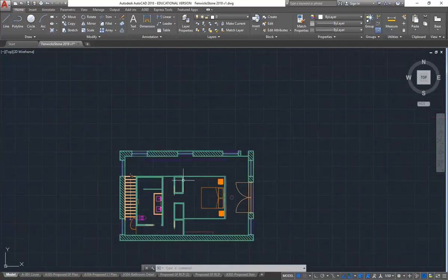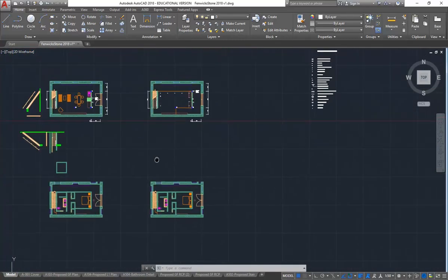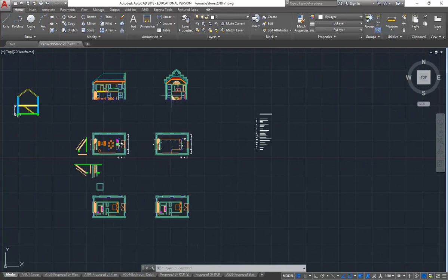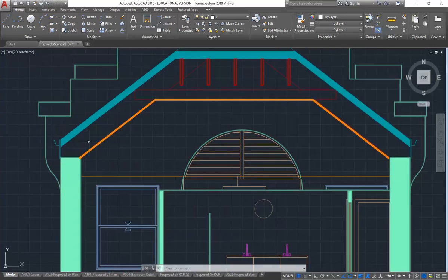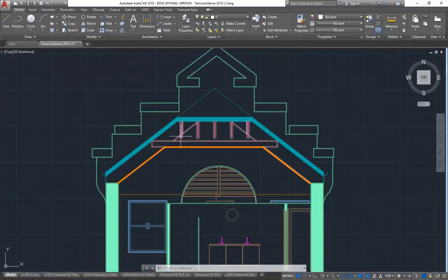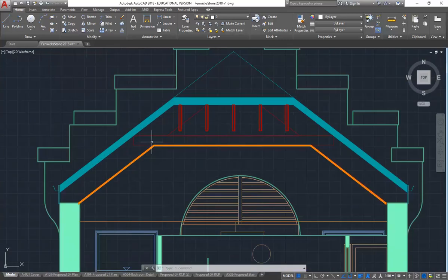Okay, so then it's basically the same idea on the upper level. So if you have an exposed ceiling structure, you'll need to show that. In my case, this would have the raked ceiling lined with plasterboard. So what you would see there is just a line where the corner of these edges of the plasterboard show.